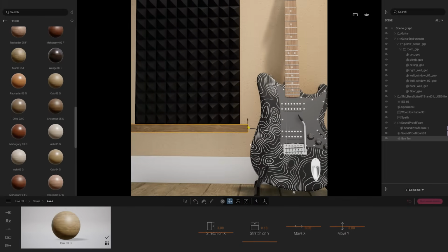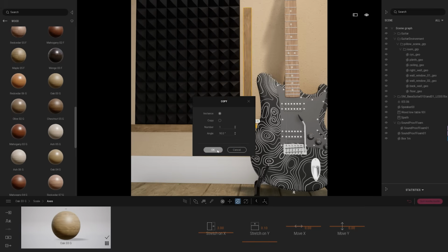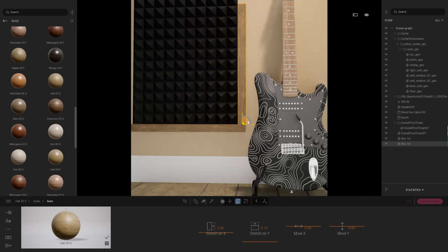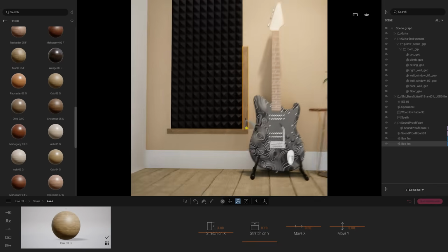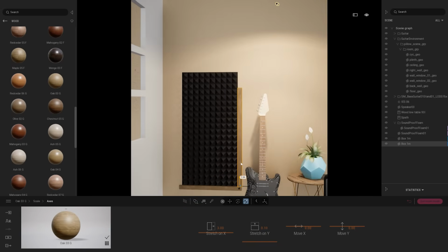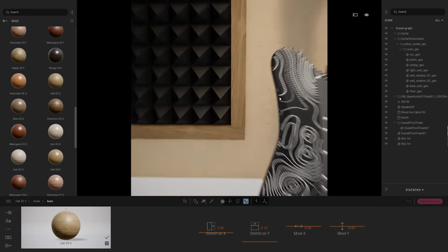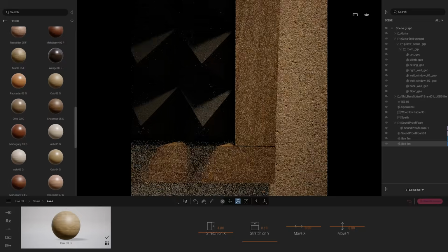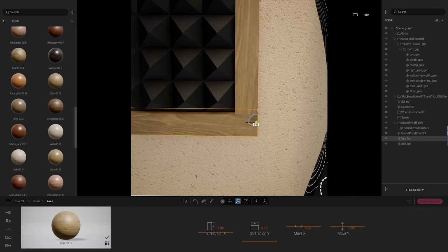So now that's done, I'm using the rotation gizmo. I will come over the rotation axis. I'm going to press Shift, click on that rotate axis to duplicate that geometry in a rotation. And I'm going just to move that toward the side, something like that. And just going to scale that one up to the top part, roughly like that. And I'm just going to make sure it doesn't touch the bottom part, just so when we have the path tracer on, it has some nice little detail like that.